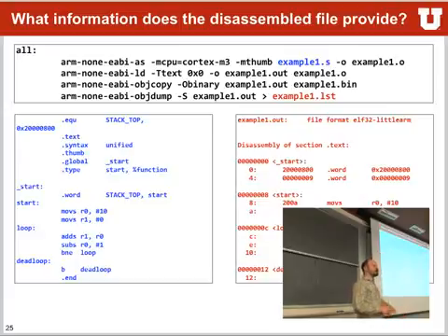And when you write assembly, you write everything with start labels, loop labels, dead loops. And what the whole toolchain does now is map this to actual physical memory locations on your microcontroller, right? So it will replace the start with 0, which is what we told it before. That's address 0 where we start. It then has the first two words. Now you can really see that the stack pointer gets read from here. Then the first jump address at 9. If you look down here, address 8 is actually our start location.